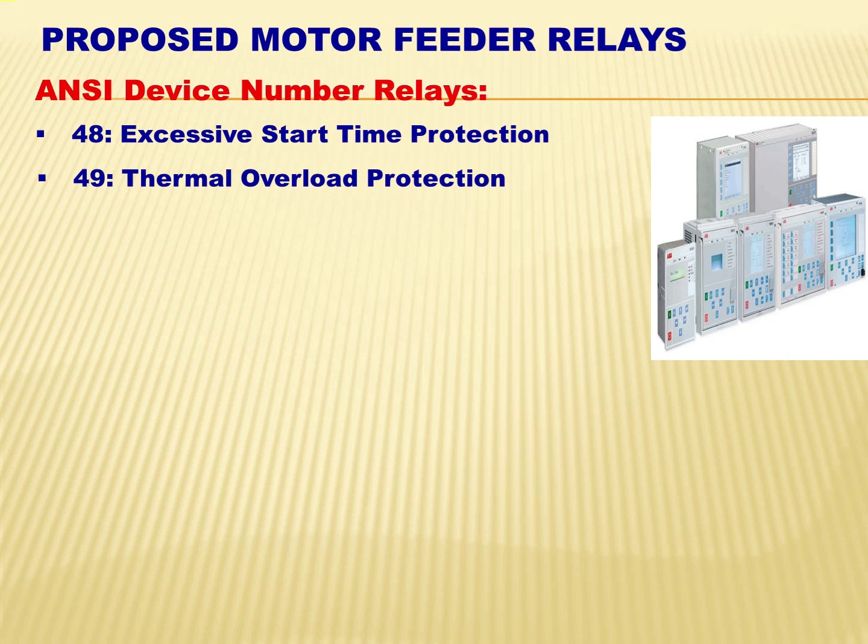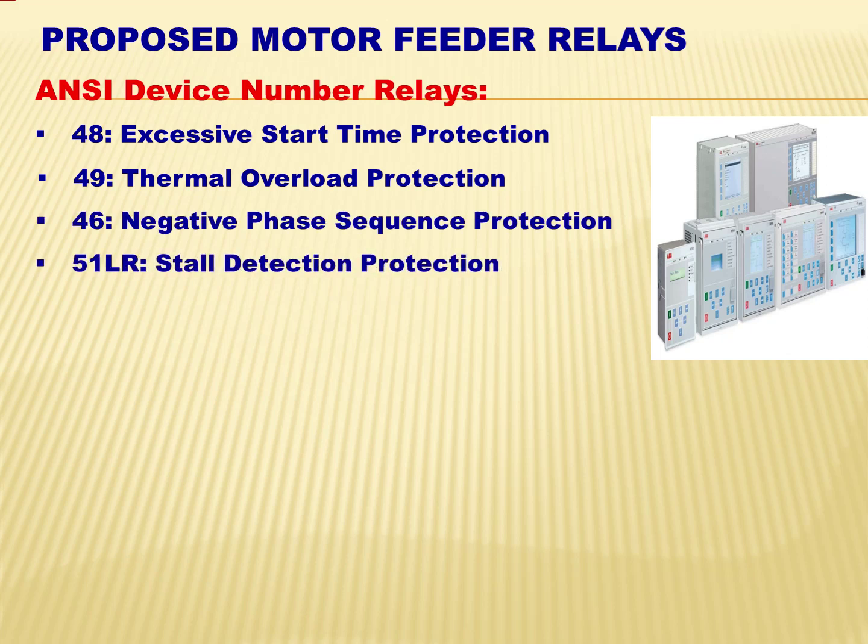Next, relay 46 or the negative phase sequence protection. The presence of negative phase sequence currents in the rotor of a motor causes detrimental heating.